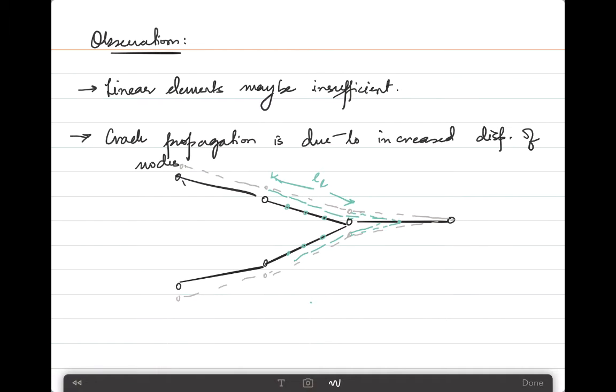Now, if I have a lower number of nodes, it also means that the forces are going to be higher than actually needed to open the cracks because a longer edge length is involved. So if the load increases, you can have further excession of fracture strength, which is also overestimating your results.